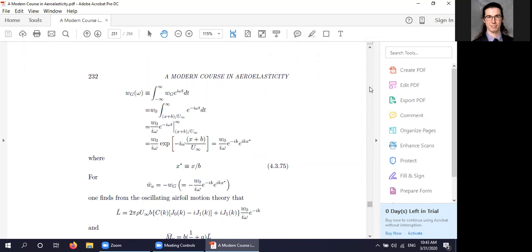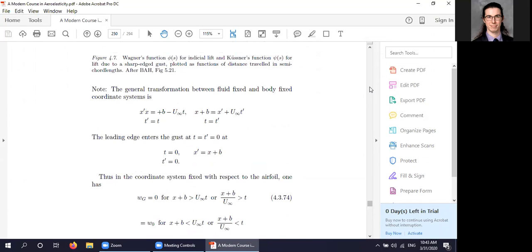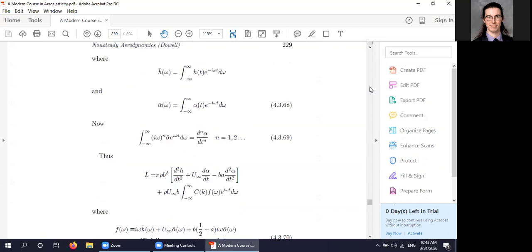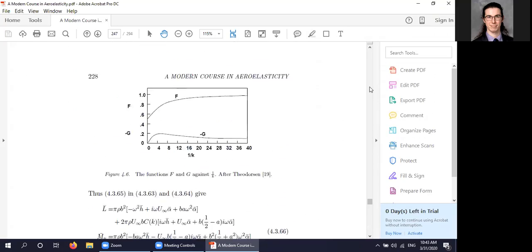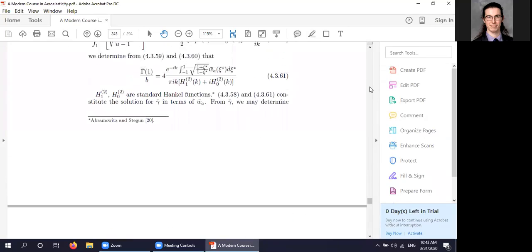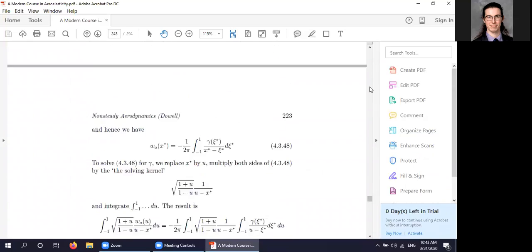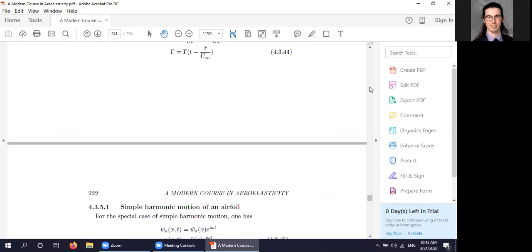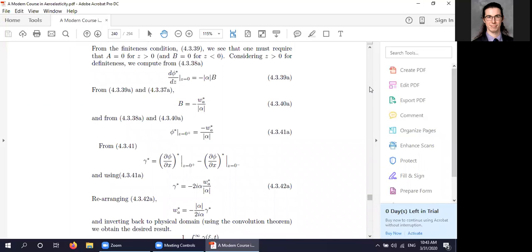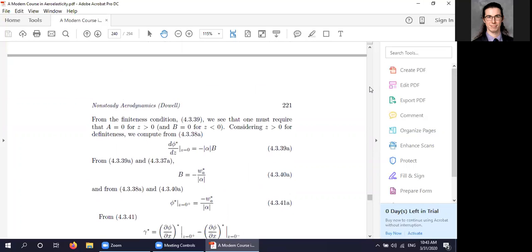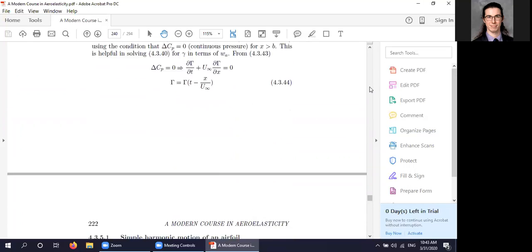Of course, from the aeroelasticity perspective, it's the difference between doing a force response problem versus a flutter problem, depending on whether you're doing the aerodynamics due to motion or the aerodynamics due to external excitation like a gust. But from the aerodynamicist perspective, it's really not that big a deal. The same code that will give you the aerodynamics due to motion will give you the aerodynamics due to a gust.